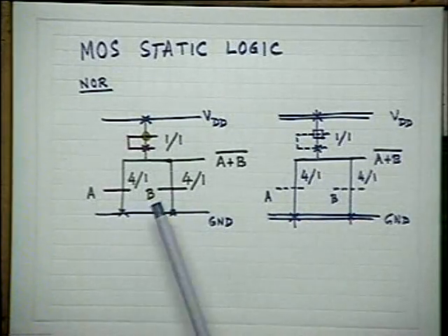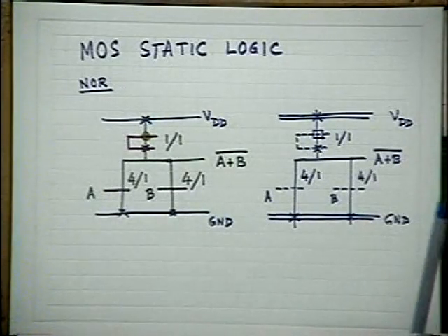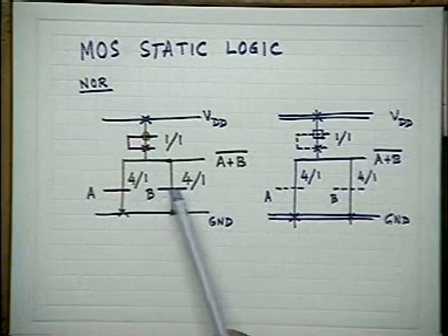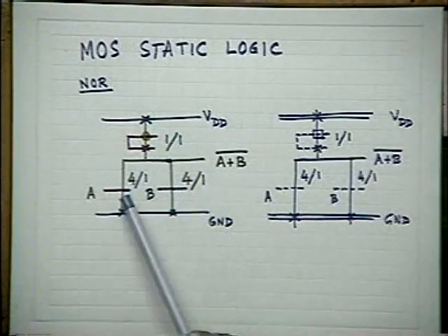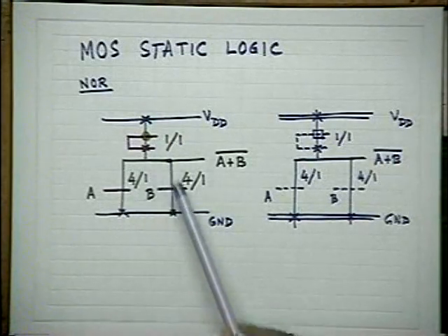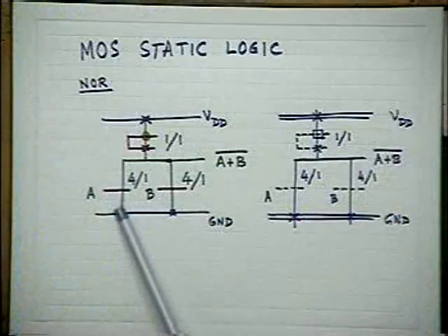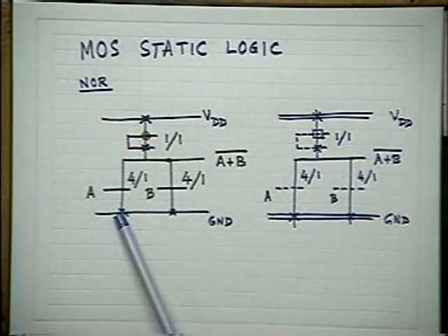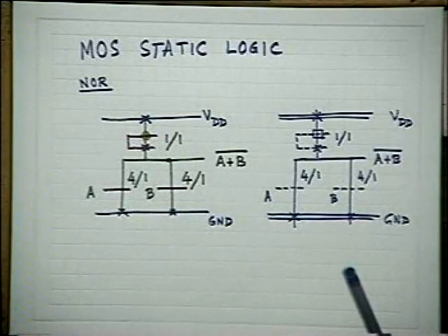So you just see now the two driver transistors which have to be used in the case of NOR logic. They have the same W/L ratio. So here, what is the value of beta R for this inverter? There are two inverters merged, is it not? In NOR logic there are two inverters merged. What is the beta R ratio of this? 4. What is the beta R of this? 4. Is it proper? You remember it is a MOS logic with depletion mode load.